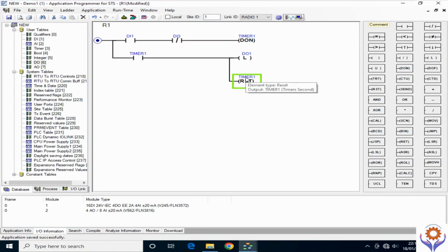So what happened after this time? Once it's latched, it will reset again, and it will wait for the second cycle. Okay. Now when the pump should be off, if there is a trip, I can put the same condition. It's reverse. See, I will put if the pump is not in auto, or the pump is trip. This is the pump trip, no? DA3. Can use DA3 pump trip.